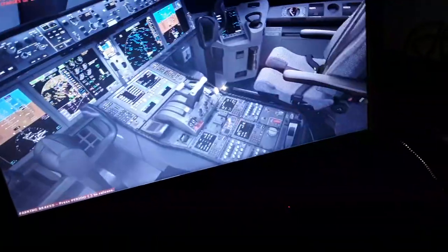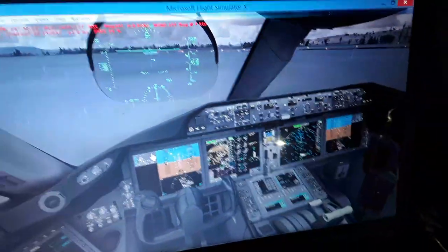So I'm going to show you, I was talking about the horizontal trim stabilizer. So I use the runway, the takeoff gross weight, the mean aerodynamic chord position, the 23% MAC of the forward wings. The aerodynamic chord position is the position where the maximum aerodynamic lift occurs in the forward wings. It's also the position where the stall begins, where the airflow becomes detached in the forward wings for a given angle of attack and airspeed in flight. So we need to monitor the stall speed over here in the primary flight display when we fly, and avoid it all the time, because it's going to make the aircraft start falling.